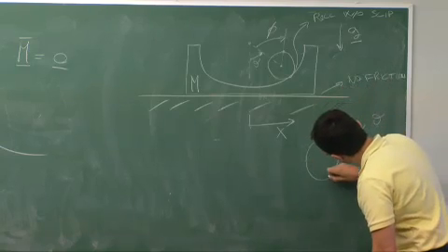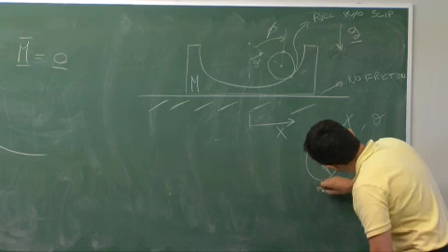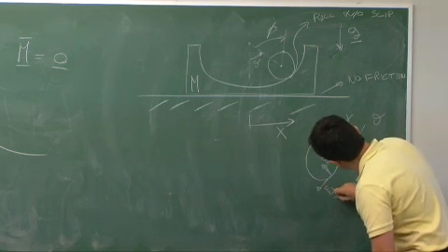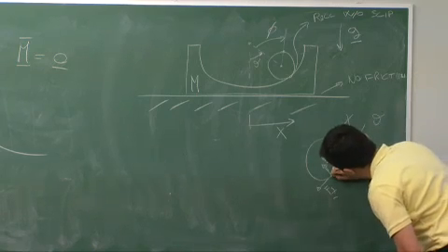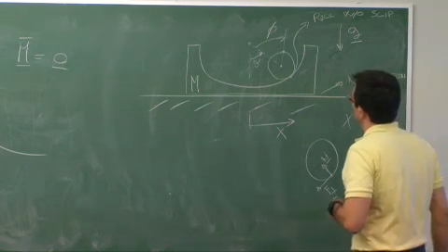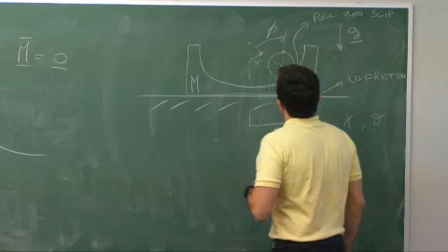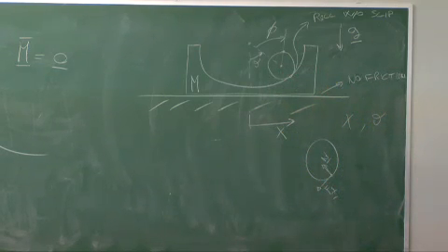The disk will see a reaction here, a friction force here that keeps the condition of roll without slip respected. So these are two constraint forces. If you do it with Lagrange's equations, they don't go there. So we'll try to do it both ways, or at least approach the problem both ways, because I think that's the best, to see the benefits of one approach or the other.